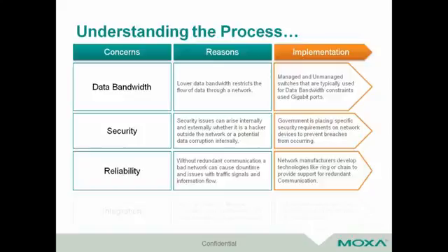And some technologies will use copper wiring. The reason I bring up copper wiring is that there are some serial communications that occur, and in some cases you don't want to rip out the two wires. If you want to communicate over Ethernet, you can actually use DSL extenders, meaning they'll talk DSL over that copper wiring and bring out Ethernet communications on both sides.